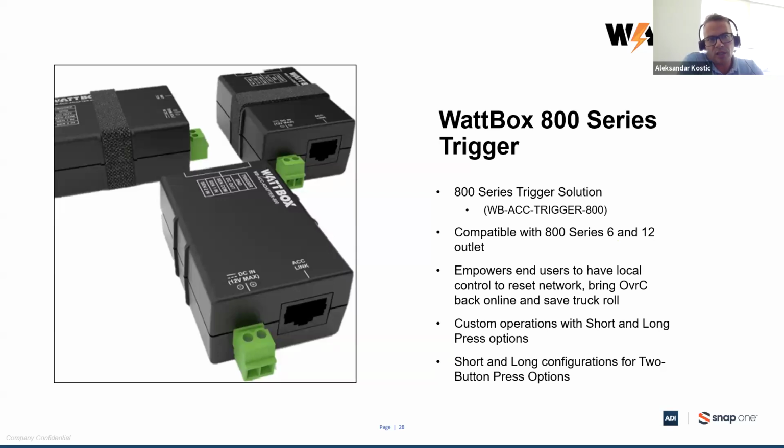Even when the complete local network fails, if you cannot reach the WattBox over the IP address, you can use the button dedicated to this trigger to reboot WattBox units which are behind in the rack. So it is just like a trigger relay contact which is rebooting the WattBox, like a last resort in troubleshooting.